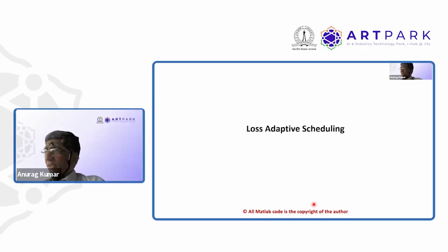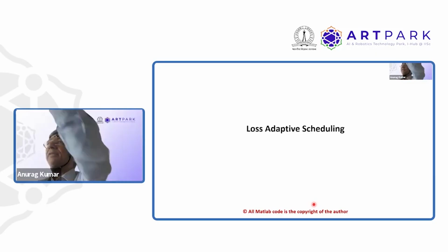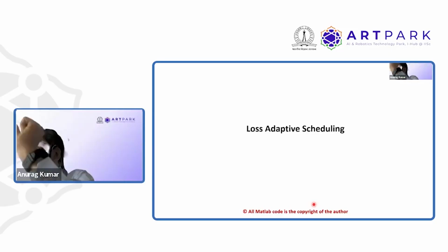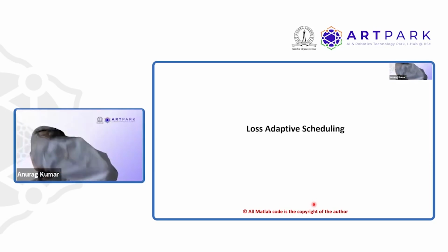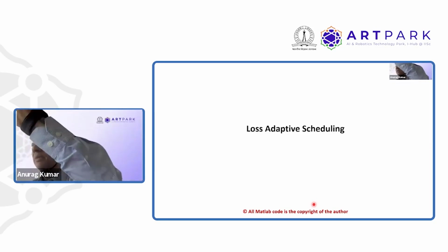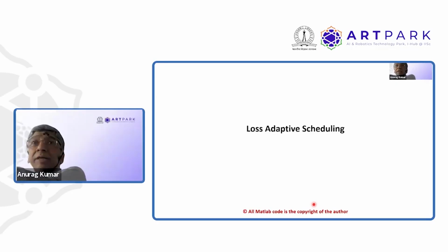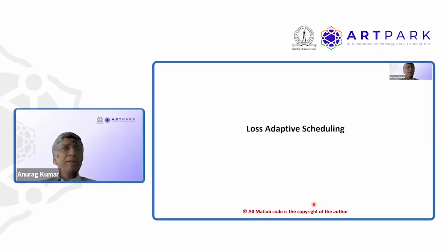But if you go back to my earlier slides for today, what do I do? I take the MCS. I hope you remember. I convert the MCS into bits per slot, by obtaining the bits per symbol and multiplying by the symbols. And then in the EWA formula, I put that entire amount into the update, assuming that whatever I send gets successfully received. That doesn't happen in practice. In practice, when you send something, it can get lost. When it is lost, that's lost throughput. You thought it had succeeded, but it didn't succeed.